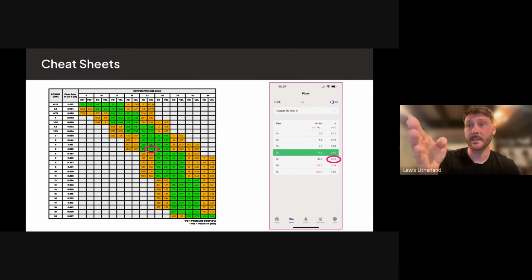And then if you go down the pipe sizes, it tells you, first bit is your pressure drop, which again, we'll talk about, but the next bit is your velocity in meters per second. Again, there's that 0.75. You've done that calculation in all them different steps and remembered all that stuff. I literally went onto my phone, did 5 divided by 21, okay, 0.24, put that in, bang, straight away. If it's 22 mil, it's 0.75 velocity.